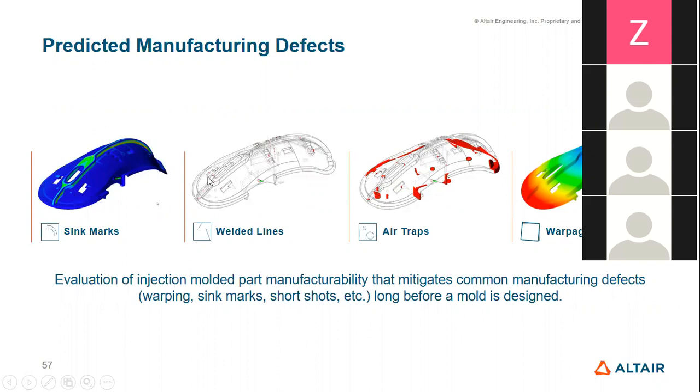Here you can see the small red color lines. Basically, when the two molten metal flows going in different directions, after some time meet at some particular location. Due to the temperature difference on these two flow fronts, they do not merge properly with each other, due to which there is a formation of a line over there. Those lines are known as the weld line. So it also impacts the structural strength of your component as well.